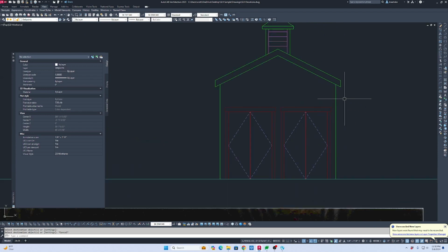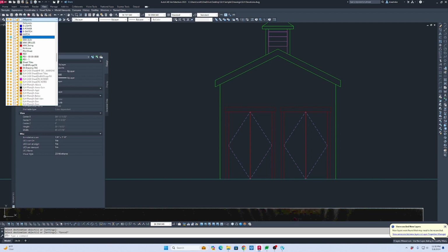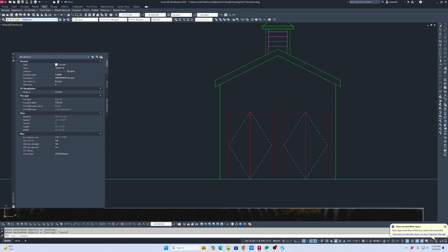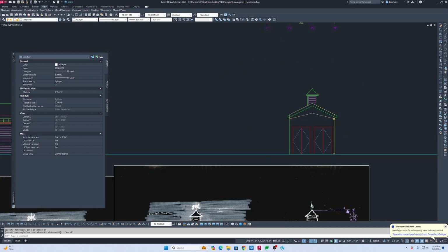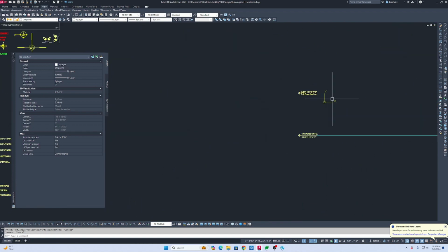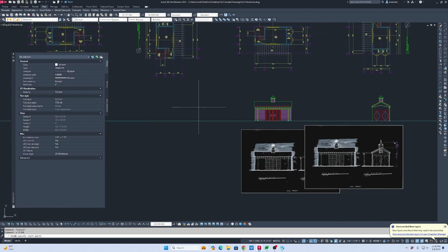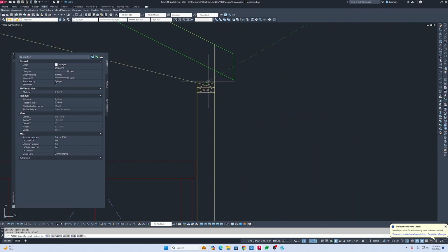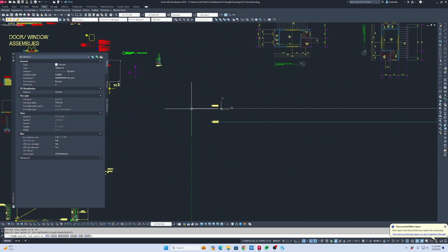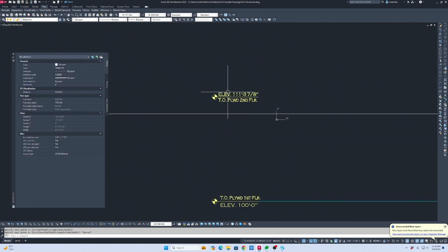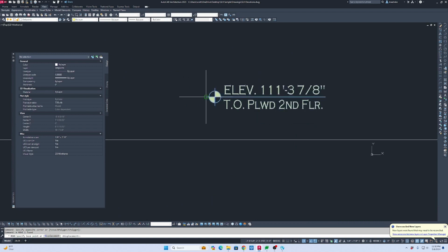We'll call that a day. So now I forgot, did I shrink that down? This is the other reason the layout layers help, because if you always know where your plate is, you can come back and, yeah, 9'6". So let's annotate that. We're going to do a 9'6" plate. If that's 100, this is 101 foot 9 and 6 inches.